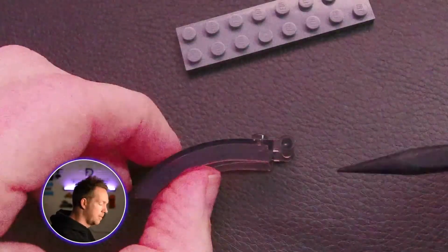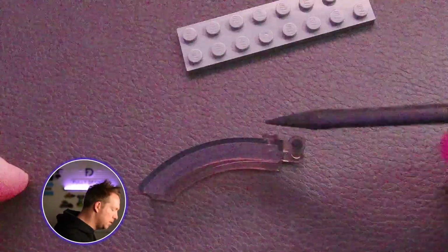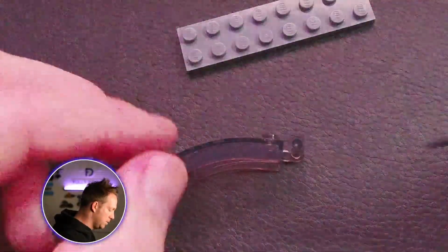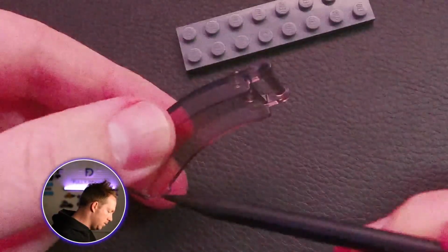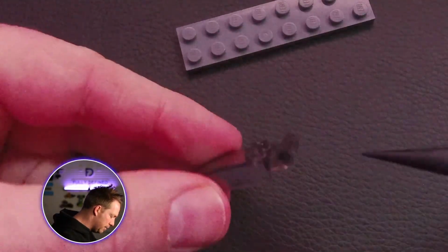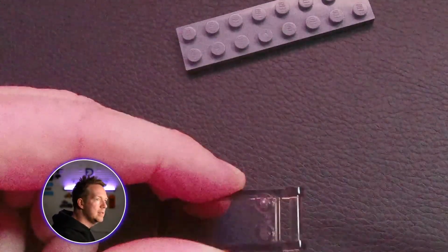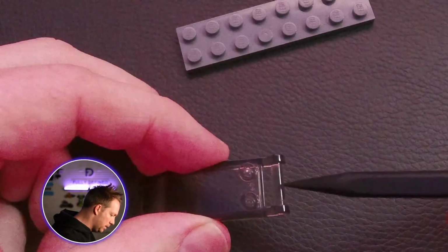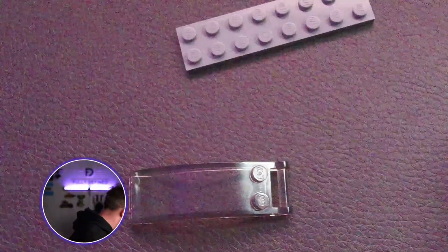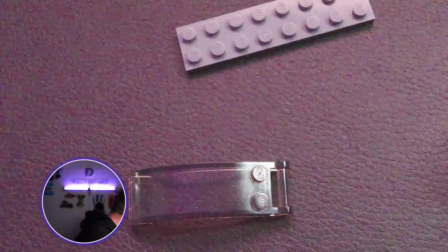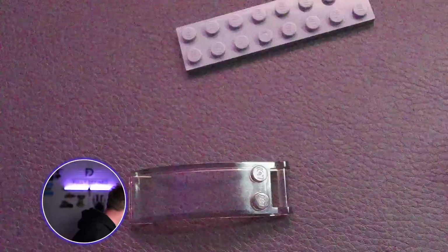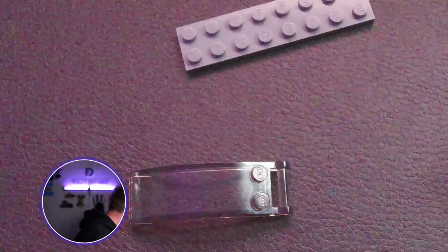I could just sketch the shape we see on this side profile all the way, or do a sketch in the middle and extrude it whatever width I need to, so this width, and then do that shell. Now with the shell, I can remove this material here and here, and then I can add on this as the next step afterwards. This is very similar detail that we see in a lot of different parts that snap together. This one, if I just find another part that this connects into, and I can't see one on my desk right now.